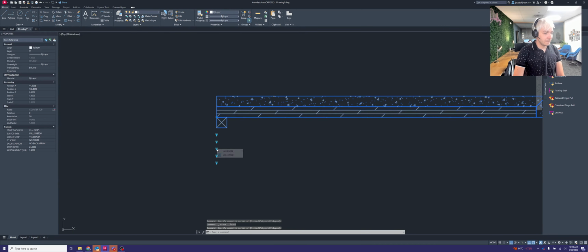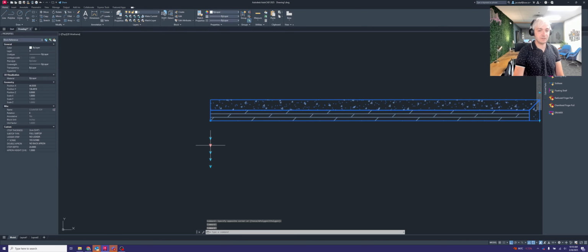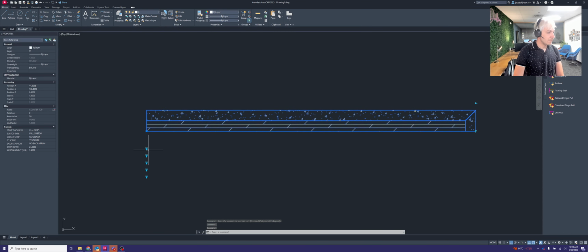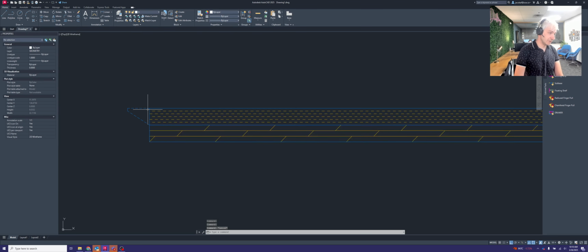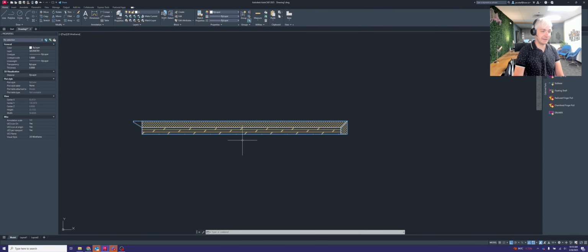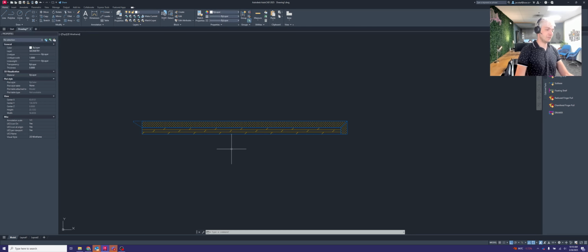All right, so we're going to move on now to scribe. Most countertops you will see don't have scribe to them. If there is a material like a veneer or laminate, we can add scribe to that countertop, and that's what that would look like. It's a 1-inch triangular piece of material added to the back of that counter. That way, if your wall is a little wavy or out of whack, you can scribe that countertop to the wall.